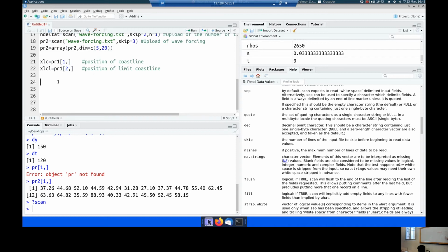What happens then? If you put this condition, here you have an accretion, which is precisely what happens with a groin, because the sediment transport potential is 0. Even if you compute a high rate, you put it at 0 for the presence of the groin. Therefore everything that comes from here gives an accretion, which is this one.